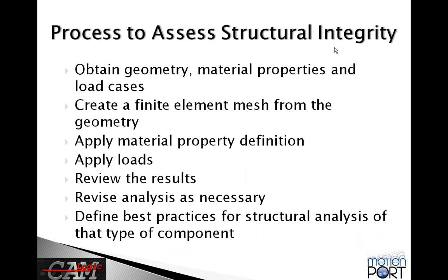So what's the process to assess structural integrity? First of all, you need to obtain these items from the previous slide, the geometry, material properties, load cases. Second, you want to create a finite element mesh from the geometry. What this will do is subdivide the geometry into small, evenly defined blocks of material that equations can be associated with.